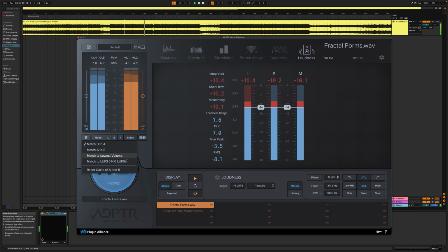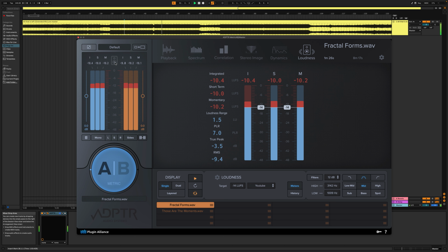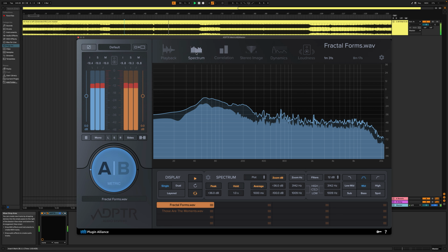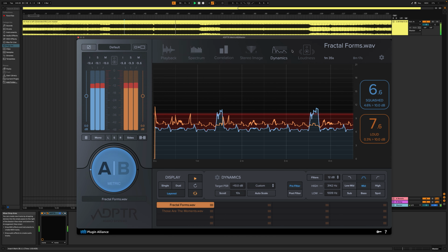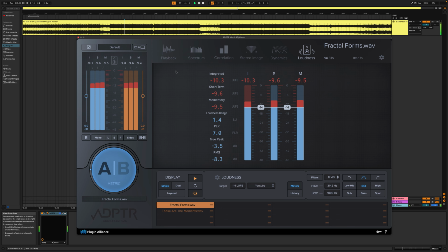And now in version 1.5, we can toggle the output meter and swap it for an LUFs meter to keep track of loudness levels no matter which analysis page we are using. To do it, toggle the peak RMS text on the output meter and it will switch to a loudness metering. And now we can see three types of loudness meters: integrated, short-term, and momentary.